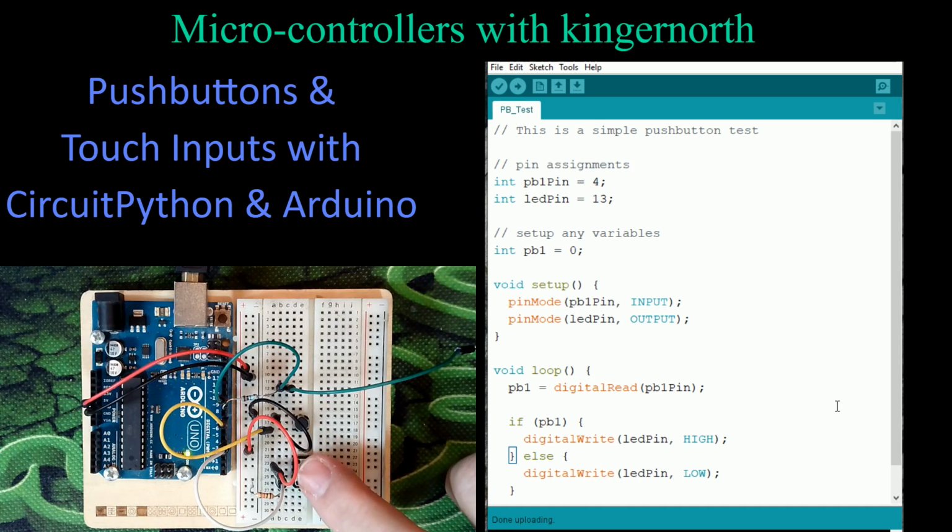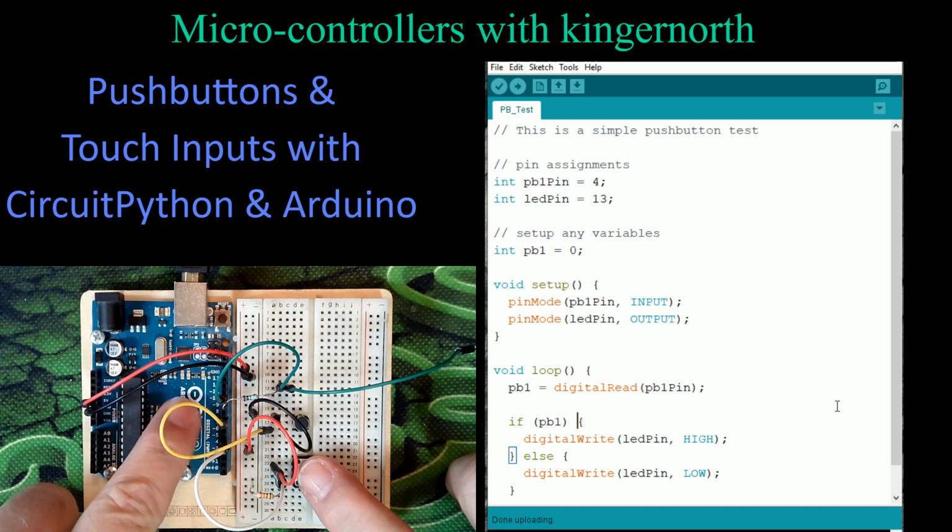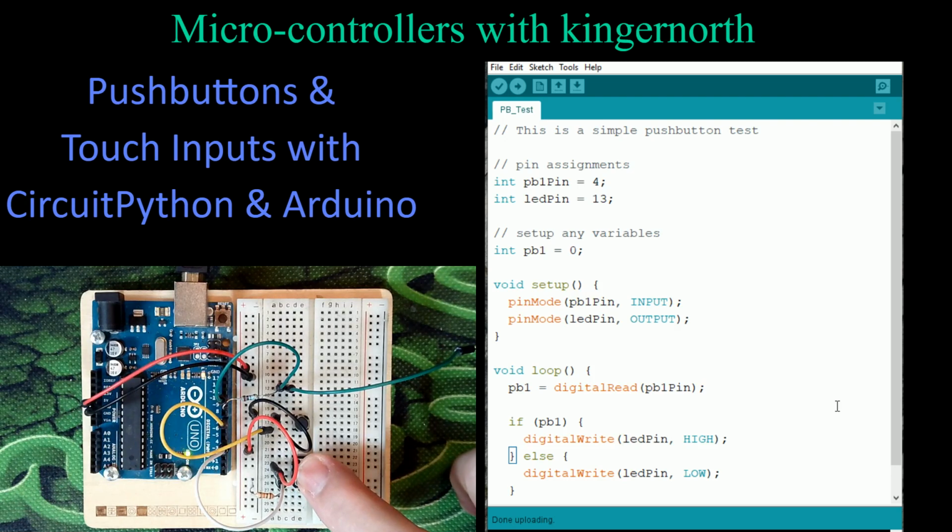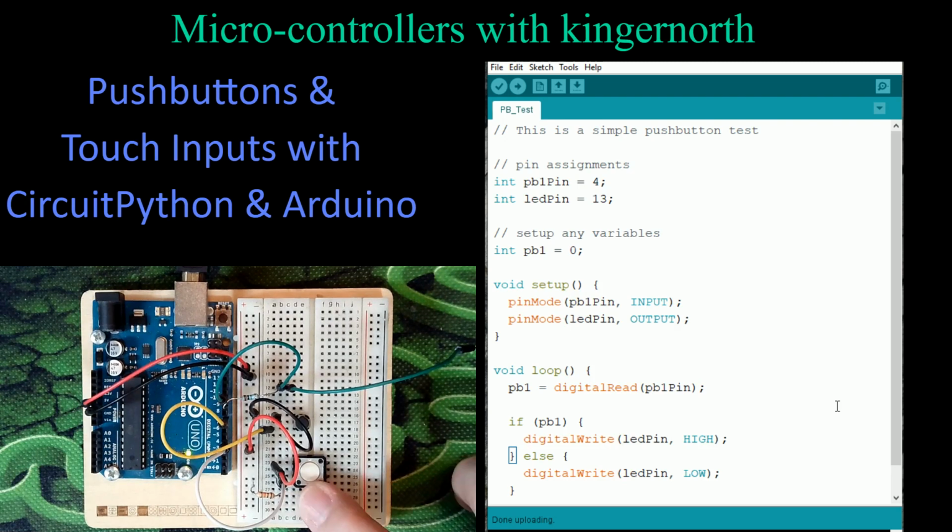If it works, when I press this button, this little tiny LED over here is going to light up, and it did. Look at that. I press the button, the light lights up. When I let go, it shuts off. It did exactly what it was supposed to do. Now I have the external 10,000 ohm resistor over here, so that shows it like that first circuit did. Pretty simple, but I get a really good plus and minus out of this, which is really, really nice.